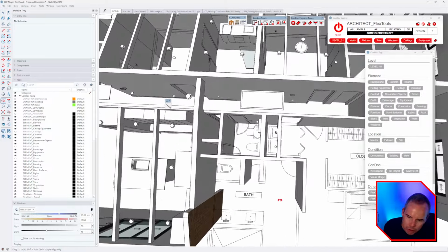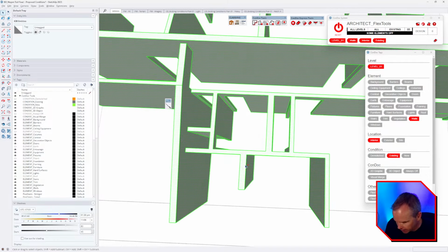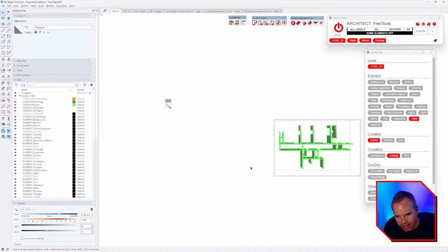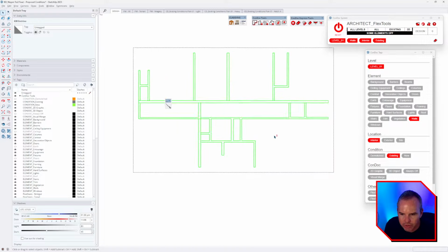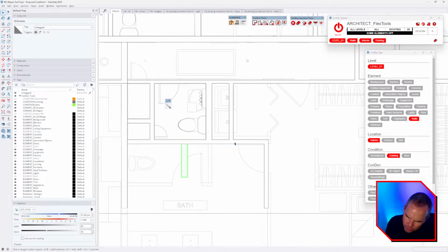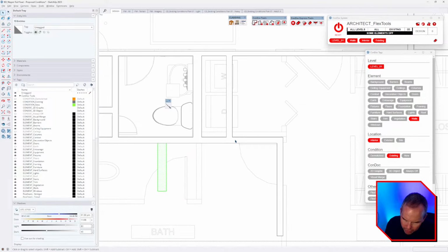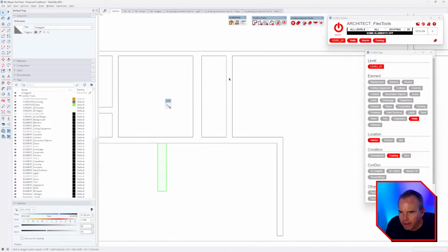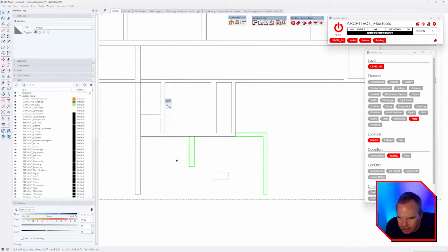All right, so same drill over here. Again, Control 1 and then F8 is what I use to get to this view where I can use my Zorro tool, and then I can slice that wall. And then we're going to demolish. I think we're just torching this whole thing. So let's just cut another line right here. So using my Zorro tool, go like this, and then I'm going to add to the selection.